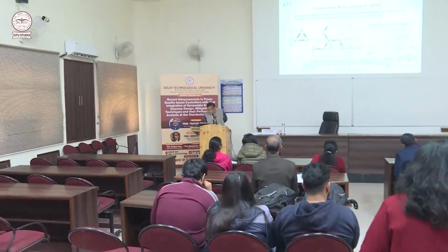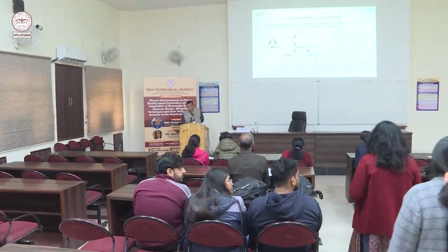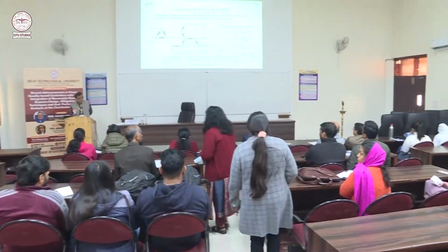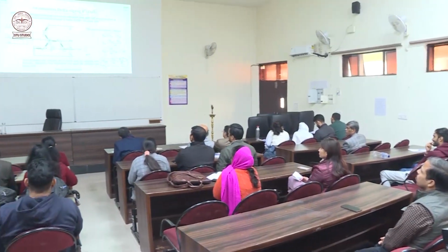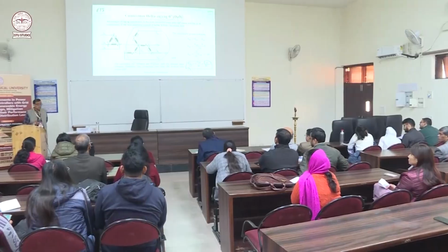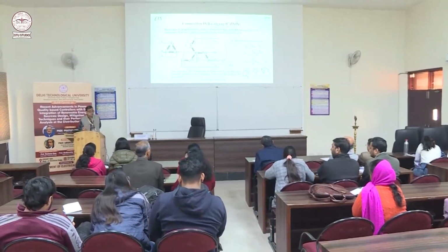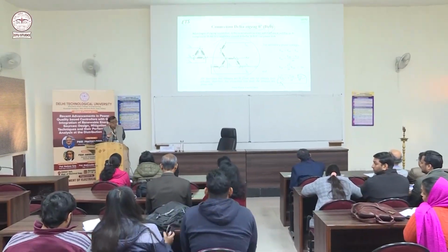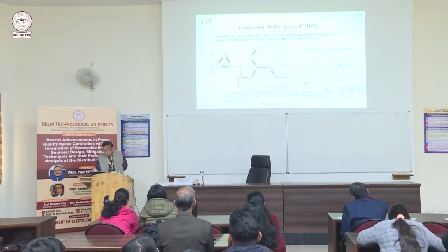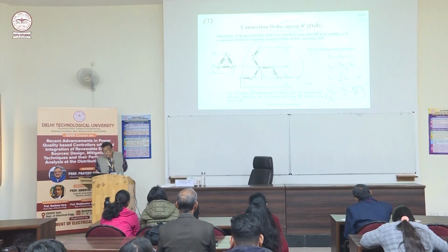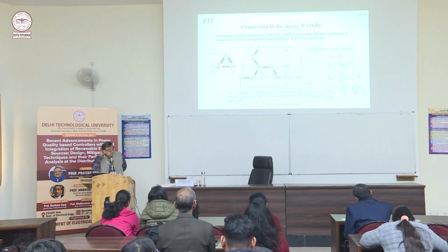But you have to see the advantages of zigzag. Advantage of zigzag we have already seen earlier. No core saturation even with half wave rectifier or DC component. So this is the advantage of zigzag connection on secondary side. If you have a zigzag connection, then your core will not be saturated, because there is no third harmonic.